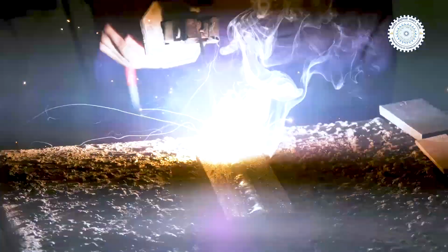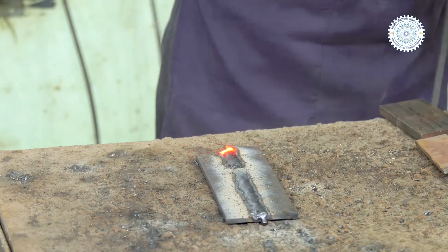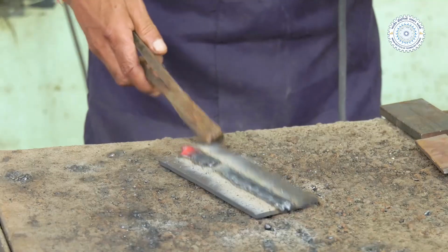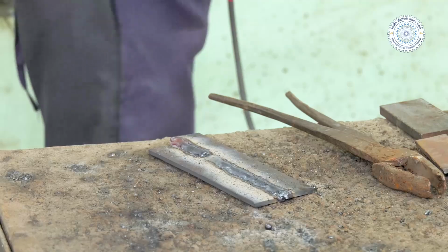This is one of the drawbacks of shielded metal arc welding, where we use an electrode of a particular length. Once it is consumed, we have to stop the process, and a new electrode is used. This brings in a little discontinuity or breakage in the welding. We may find that the location from where the next electrode has been used for welding may be full of discontinuities also.